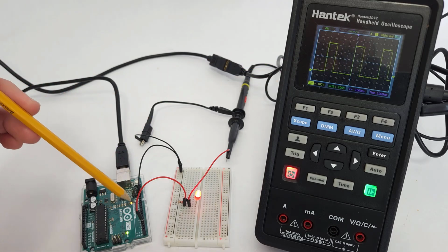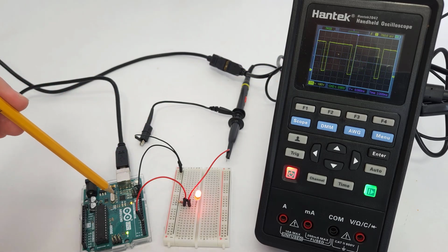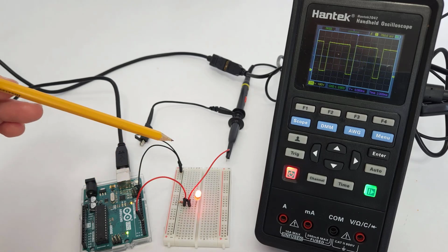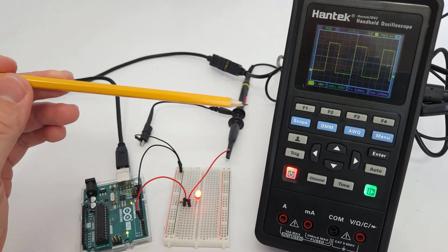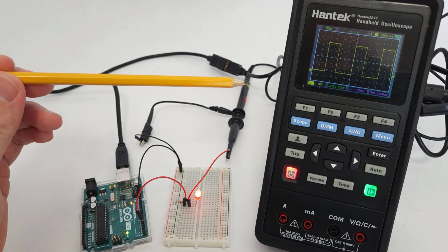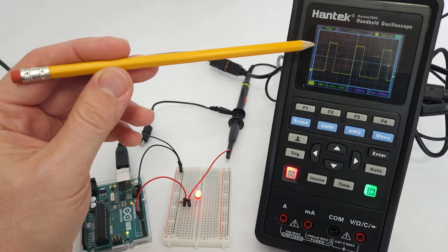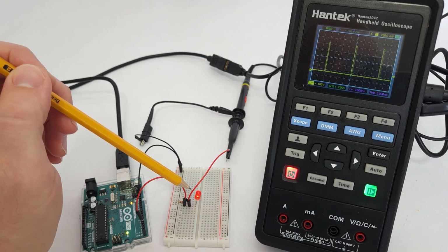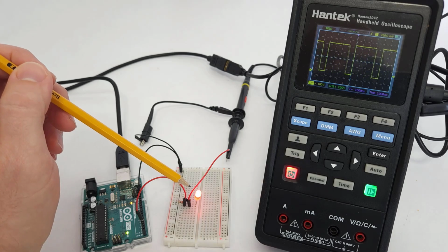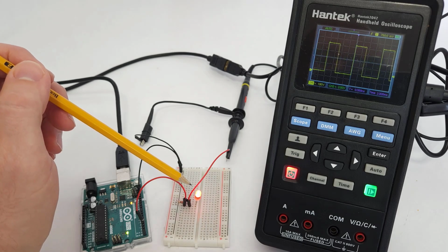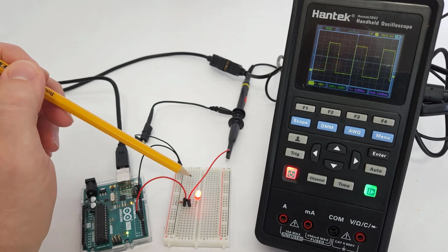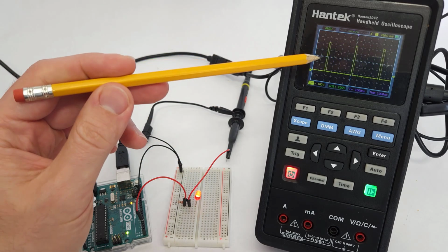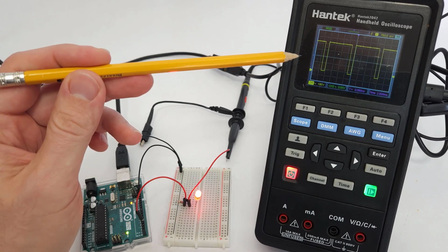At least that is true for the pins on the Arduino UNO R3, and most of the pins on the newer UNO R4, which does have one true analog output pin, but that's a topic for a separate video. So what this PWM signal is doing is rapidly turning the pin on and off, but the frequency is high enough that the human eye cannot perceive the flicker. So rather than seeing the LED blink or flash or turn on and off very quickly, I just perceive it at a lower brightness when it's not on 100% of the time.